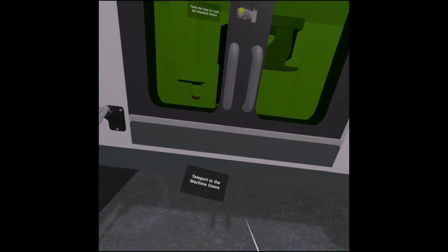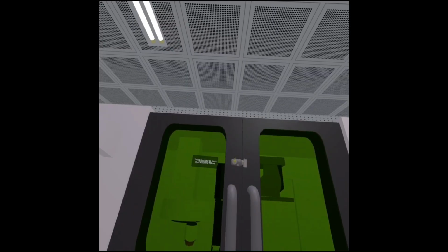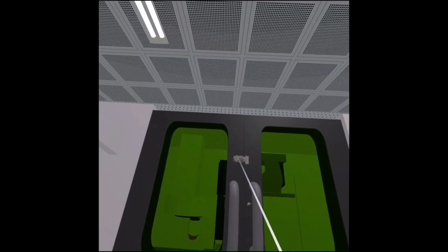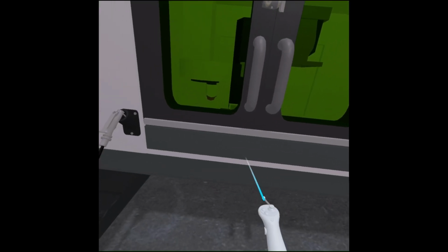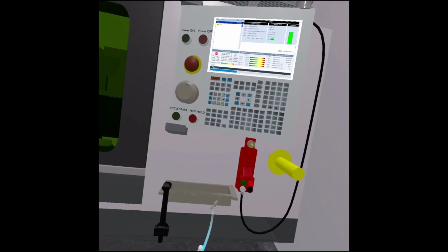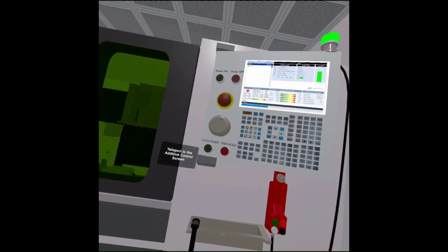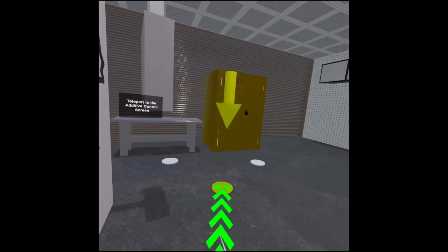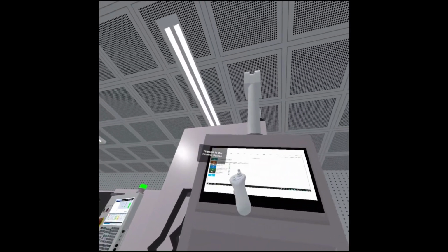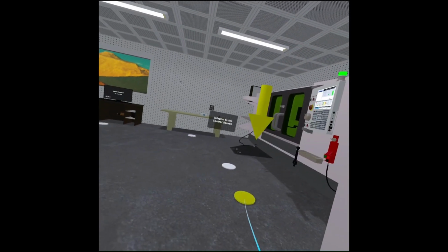The user now locks the doors to the fabrication area to prevent them from opening during fabrication. The fabrication process involves metal shards, lots of heat, and gases that the operator should not be exposed to. The key is then placed into the laser controls to enable the laser for the additive portion of the fabrication process. The additive control screen is checked to ensure that all necessary systems for additive printing are operational.